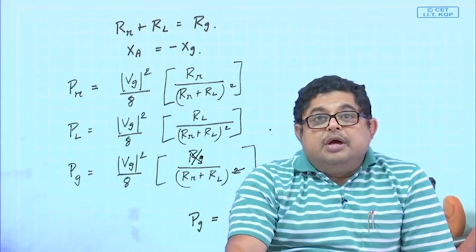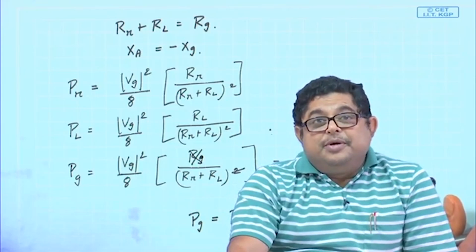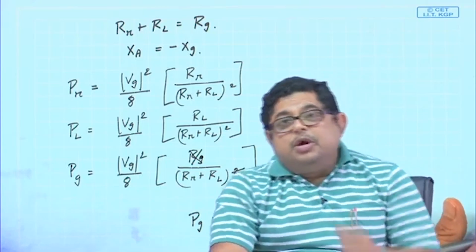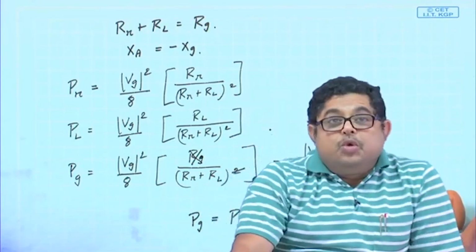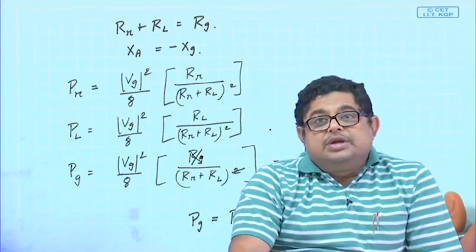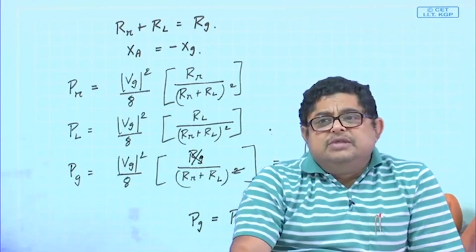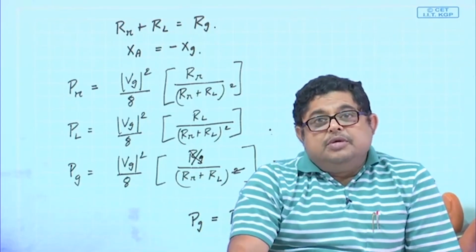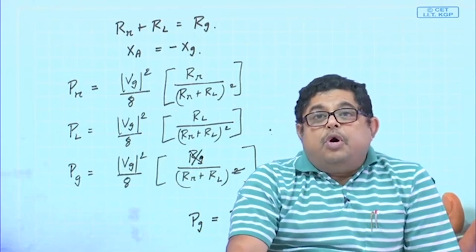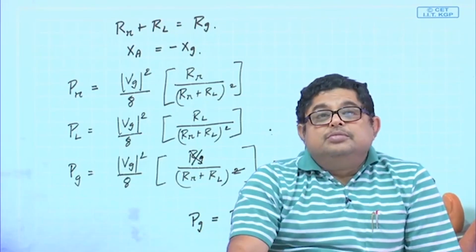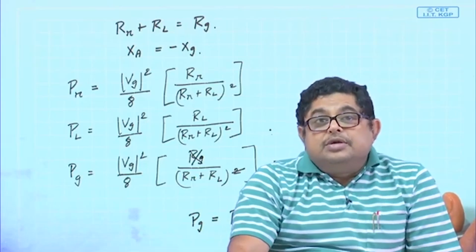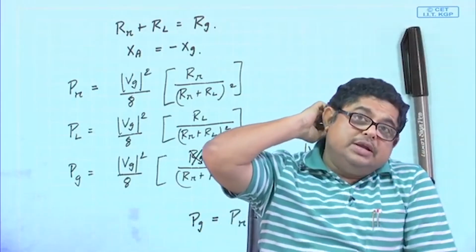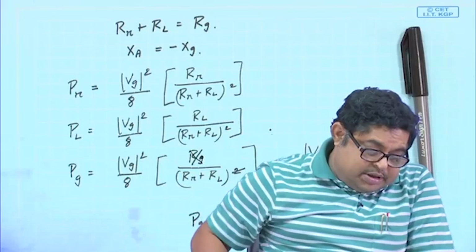So, that is why we always try to use a very good conductor, if you want very small loss, then you can have gold or silver. Actually, silver is the best one, but silver cannot be machined easily. So, you can use gold for making antenna, or you can use copper for making antenna, and also very low loss dielectrics are used. So, that this R L factor is very small.